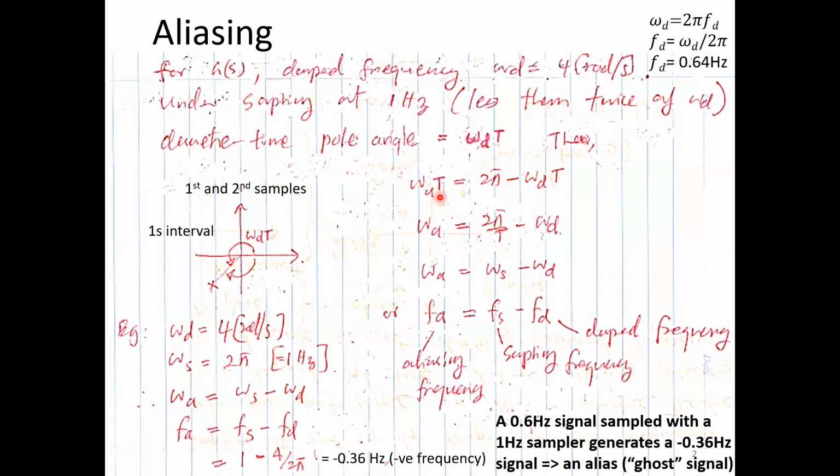So there are two processes: a counterclockwise process and a clockwise process. The counterclockwise process is faster because it goes a long angle in 1 second. The clockwise one, which is fictitious, is slower. Therefore it goes a small angle during the same capital T time. So is that clear to everybody? This equation up here: omega A was not there in the plot. The signal was omega D. This is the genuine signal. And omega A is not a signal that was there in the plot. It is a fictitious, created waveform, and it is a negative frequency also.